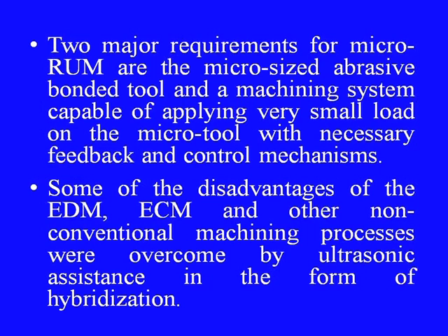Some of the disadvantages of EDM, ECM and other non-conventional machining processes could be overcome by ultrasonic assistance in the form of hybridization. Nowadays, ultrasonic vibrations are being used successfully to enhance the machining capability of even micro EDM to handle otherwise difficult to machine materials like titanium alloys.